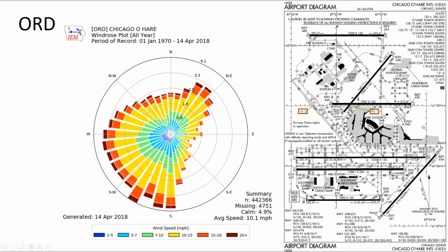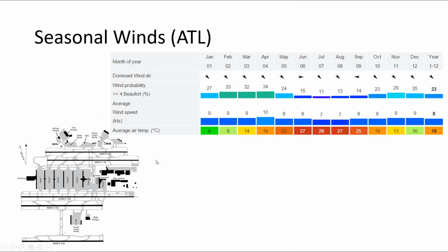And it's mostly larger aircraft that can handle more crosswind, so it doesn't have to be as perfect. But this is the wind rose there. And yeah, when they had lighter aircraft, some of these runways may have come from that era. And so they didn't line them up with the primary wind direction, right, for that. And now they say, well, east-west is good enough. Yeah, we can handle some crosswind because we've got big planes coming in there. So that's a wind rose for O'Hare, right?